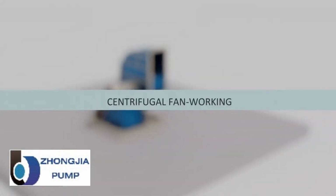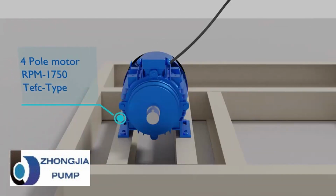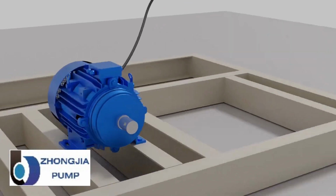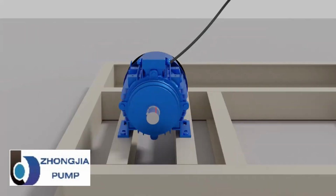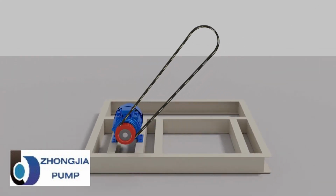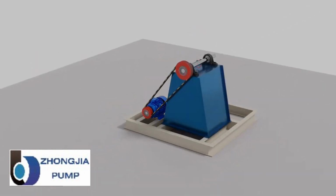Now we will see the working of a centrifugal fan. Here a 4-pole motor with an RPM of 1750 will serve power to the fan. As the electricity is passed to the motor, it starts rotating. The smaller driver pulley keyed to the motor shaft starts rotating. Power is transmitted through the belt to the bigger driven pulley. The shaft keyed to the bigger pulley starts rotating.